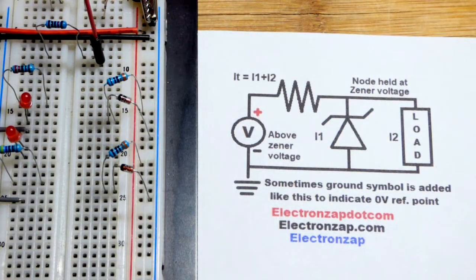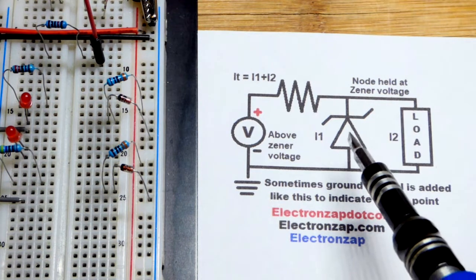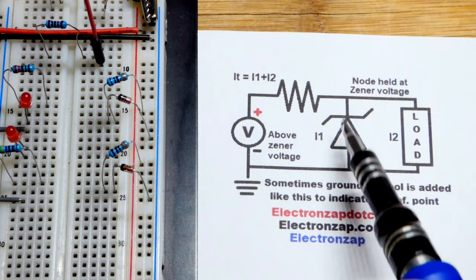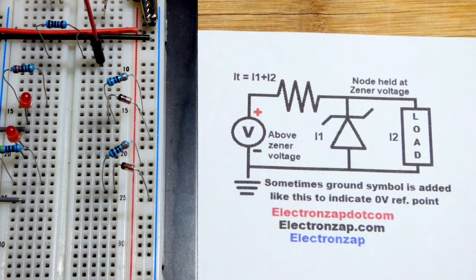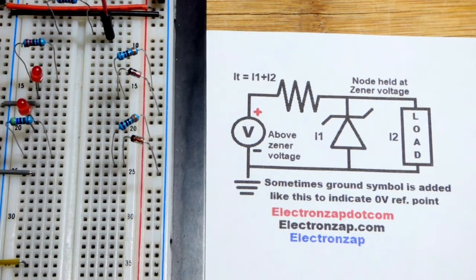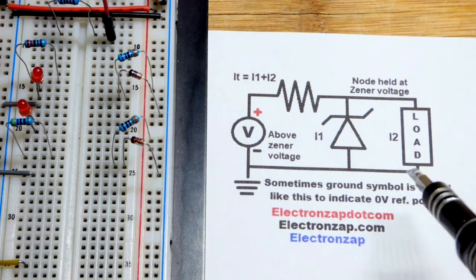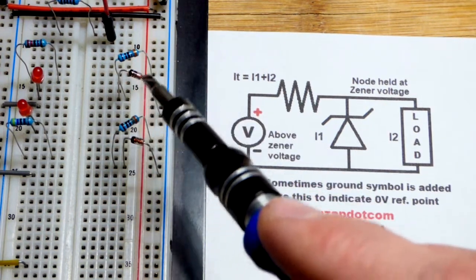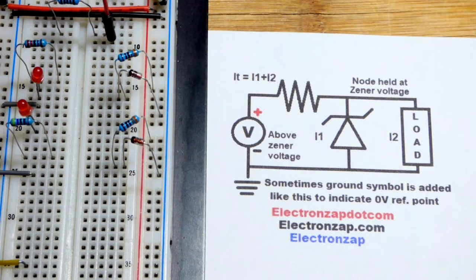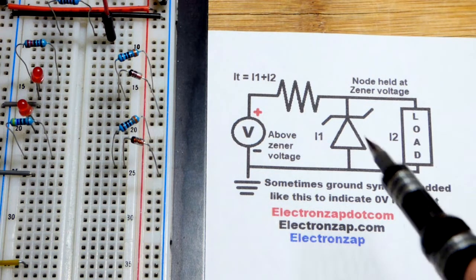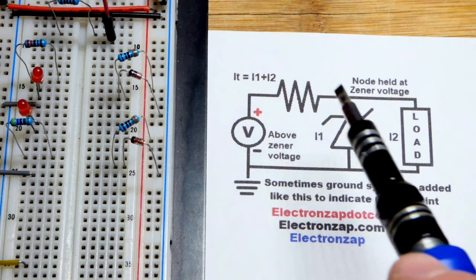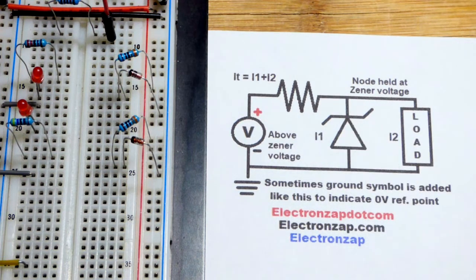So you grab the voltage zener diode you want. Use it reverse bias. Normally you're told don't put current through a diode reverse bias. Zener diodes are made specially so that you can do so. So that is one of the exceptions. In any case, the load can be what you want. Just realize that you got to have a resistor to limit current through the zener diode. Once it reaches its zener voltage, it will start conducting current freely as needed to hold the voltage there. So you still need to limit current or else you'll burn out the zener diode.